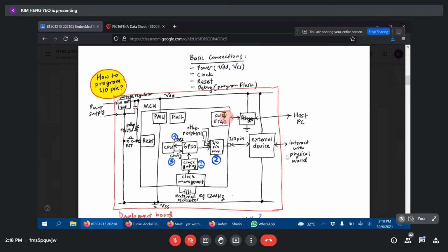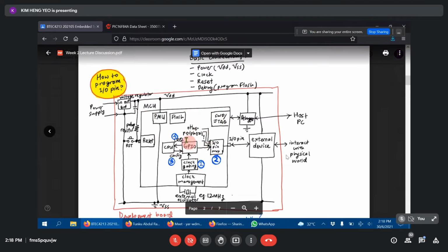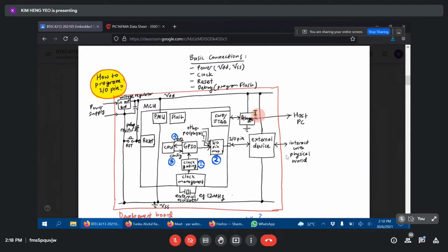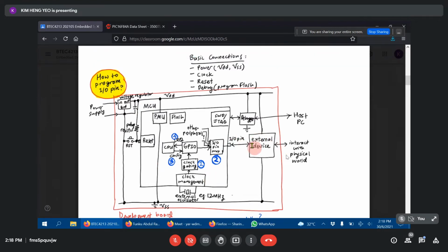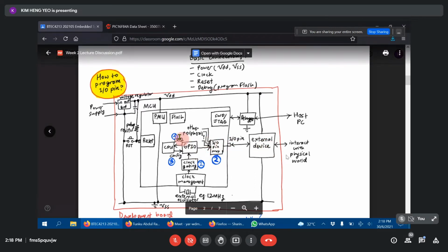In order to connect to the debugger, the target microcontroller needs some internal support circuitry to support the debug connection. Just like to support connecting to external devices like LEDs and switches you need I/O pins circuitry, the GPIO port circuitry, you have debug supporting circuitry inside.